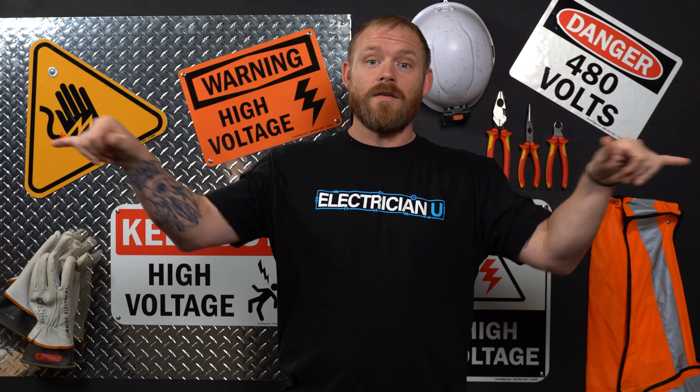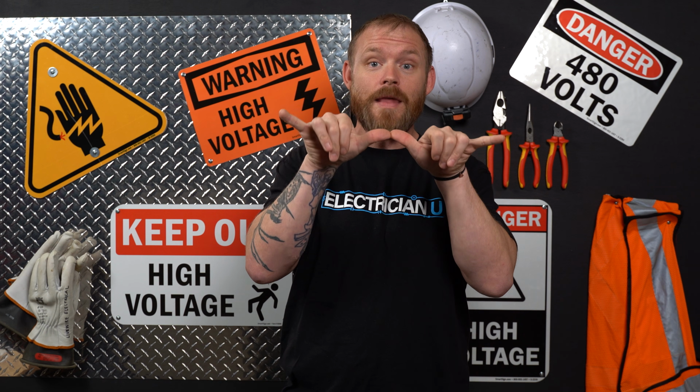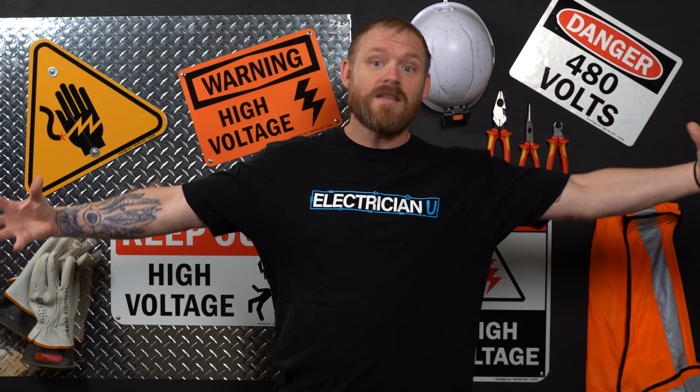Another danger with batteries is thinking about whether or not batteries are in series or in parallel. When you have a whole bunch of batteries in series with each other, you increase the voltage. So if you have a 1 volt battery and a 1 volt battery and you stick them together end to end, that means you have 2 volts. So when you have a whole string of batteries at some data center or something that has UPS backup power, you can have a tremendous amount of voltage.